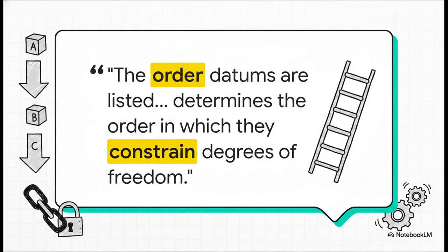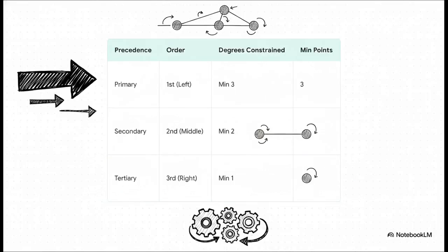Okay, before we go any further, I need you to pay super close attention to this next point. The order in which those datum letters appear is about to completely change everything you think this callout means. Datum precedence is read strictly left to right. It is not alphabetical. The very first letter you see is the primary datum.